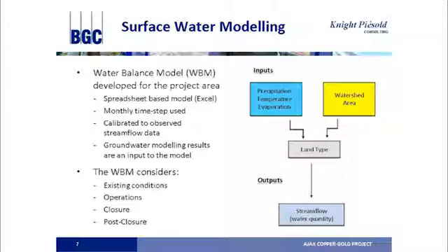It's not overly complex, but the model does a good job of simulating stream flows, both during the summer and the winter. And how it's set up is I'm not looking at stream flows on an hourly or a daily basis. I'm actually looking at them on a monthly basis. And the most important part of the whole modeling process is calibrating the model to observed existing conditions. So that's what I do initially.